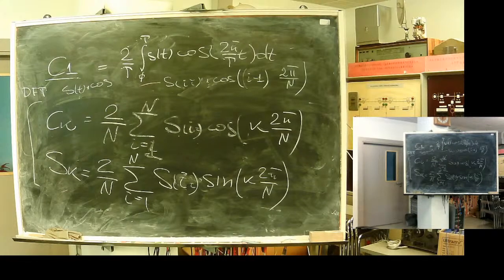See, there is one moment. We by default consider equal steps between elements in the table. All digital systems work with equal steps. But in theory, we can work with a variable time step, like exponential or adaptive. It is one way to compress information, let's say sound compressing: use the derivative of the signal to determine the time step. When it changes faster, the time step is shorter. Slower change, we can take bigger steps, so it will produce less data. Not in our business.